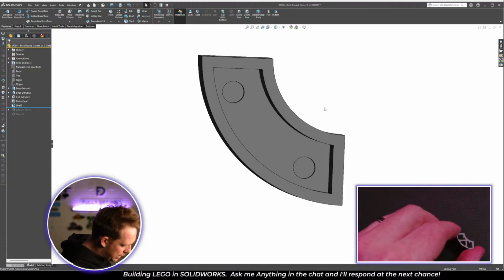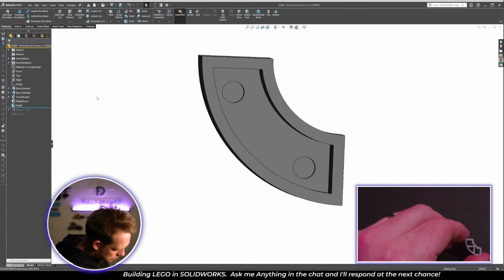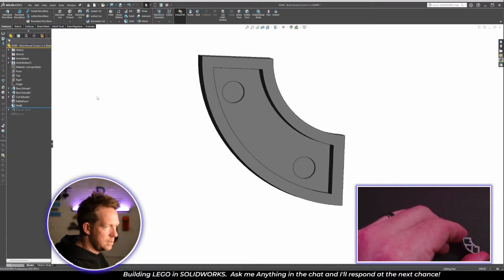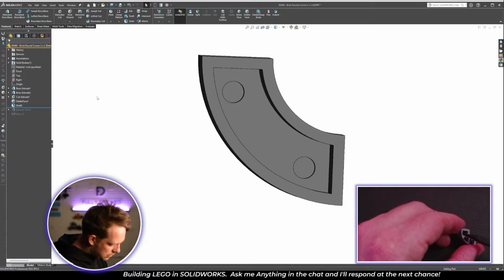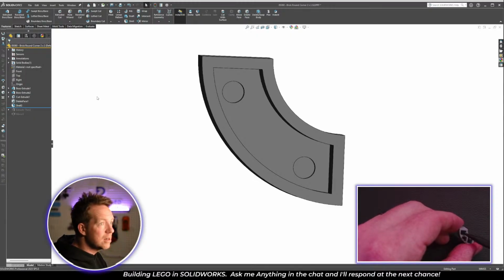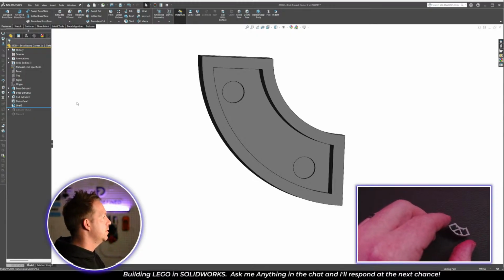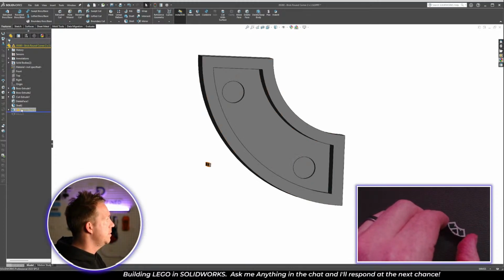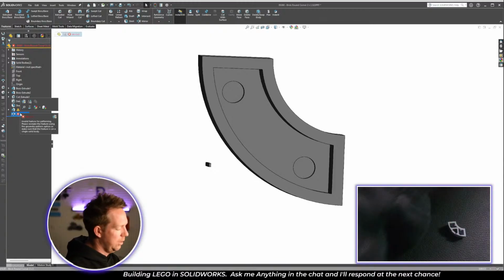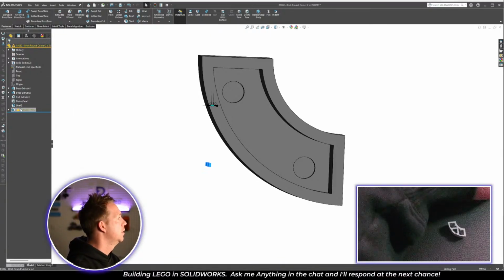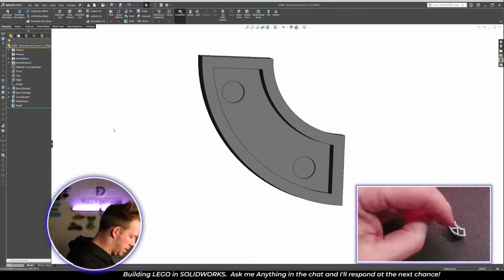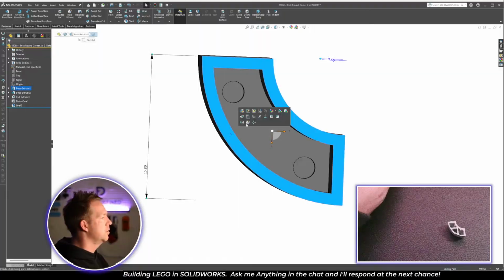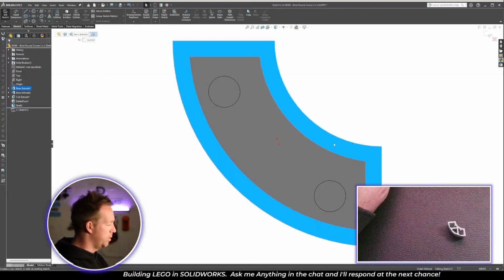And then we want to add a bit of extra detail. It's interesting, you can see the shell here, it's not consistent. We might find later that we get some interference in this area. If so, we'll deal with it then. This has a couple of ribs, and this mirror, I'm going to get rid of those. And instead, I'm just going to add in those structural elements. So I'm going to go to the top face here, the bottom face,